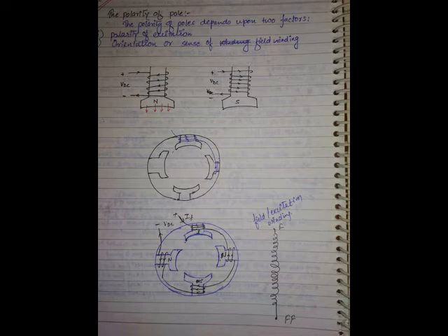These currents are actually unwanted currents. The currents flowing in the solid core cross-sectional area simply circulate within themselves continuously and produce temperature rise. Temperature rise means some part of the input energy is wasted as loss. This temperature rise is important not only because of reduced efficiency. The problem is that the rise in temperature will destroy the machine. There are many factors why losses are important, but in top priority you have to give temperature rise.